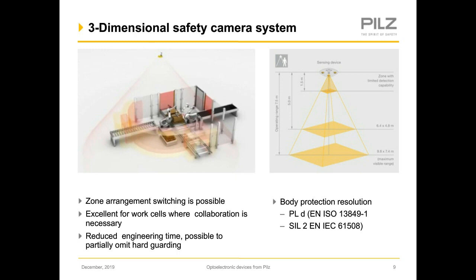So this is a three-dimensional device that has a warning zone and a detection zone, and you can create those zones depending on the results of your risk assessment and the specific calculations on these zones. So the specific width of the warning and detection zones needs to be calculated. That's an item that is good to use. For example, if your machine cell or machine itself needs to be repositioned in your workplace or on the plant floor, this unit can be moved like a light fixture with your application.